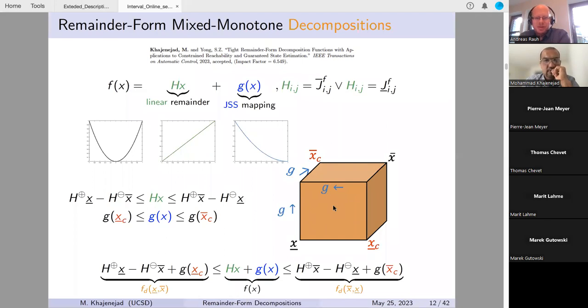If yes, you could determine a system that has linear dominant behavior, but this matrix H would efficiently be described by a bounded matrix. For example, parameter uncertainty. You have constant but unknown parameters included in your system model. And then you could use this representation. You could either shift this interval uncertainty to the matrix H, to the green term, or you could shift it to the blue term, to the term G.